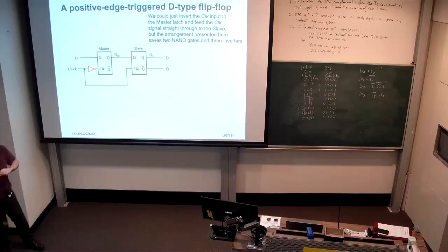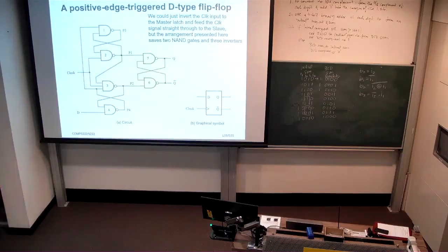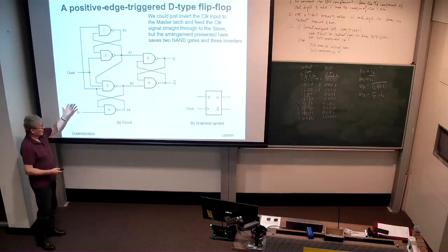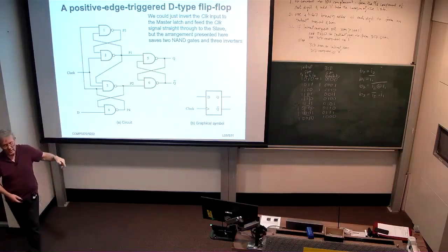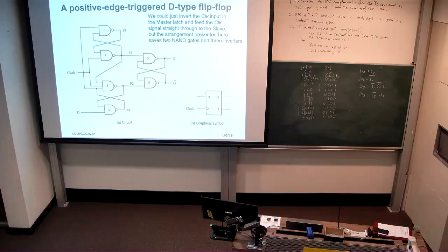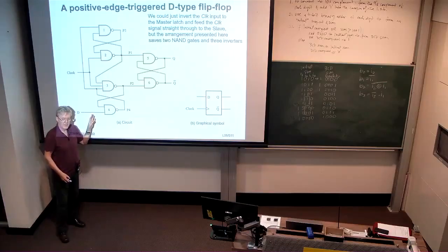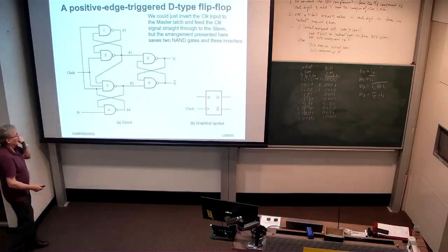We also looked at a positive edge-triggered D-type flip-flop, which conceptually is a more complex looking circuit, but it saves on hardware and is therefore desirable. Of course, the negative edge-triggered flip-flop has a comparable 6 NAND gate design as well. It isn't usually implemented using master-slave latches.